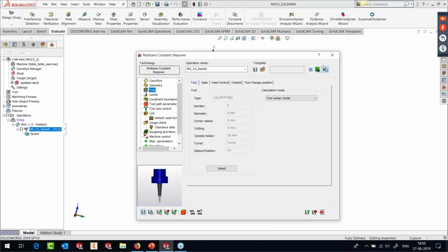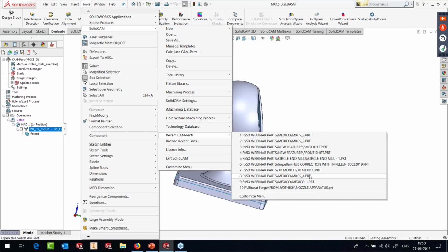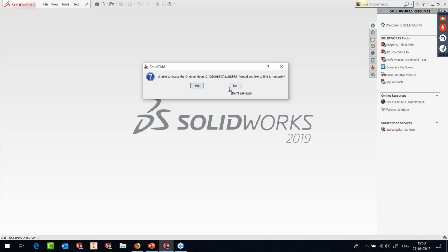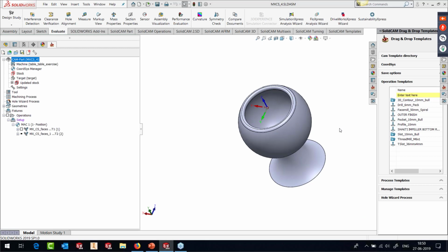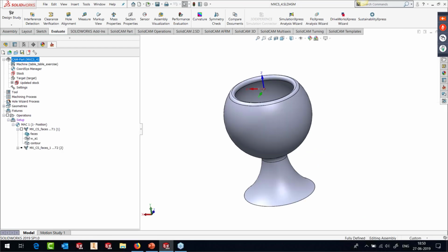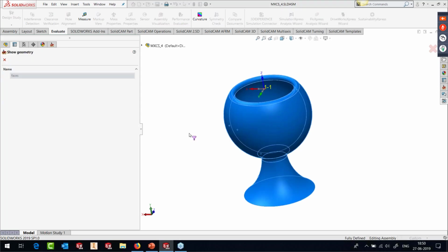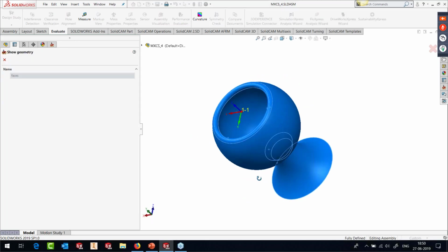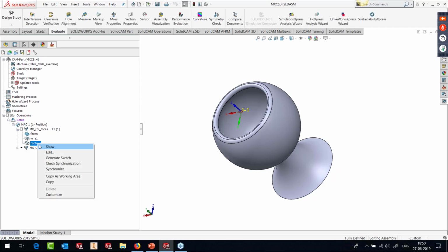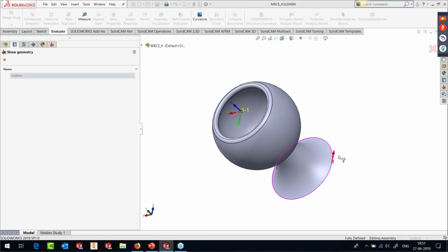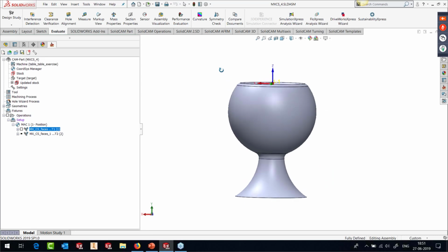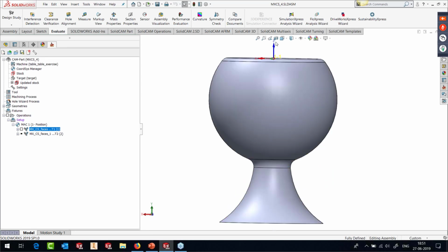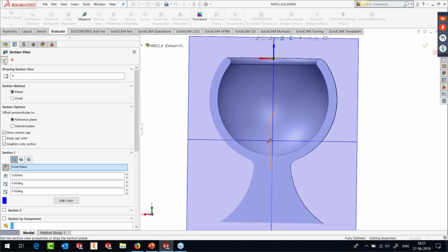We'll see another group of part or another part where it's even more nicer. Okay, in this case, I have defined a group of surfaces. Except the bottom, I've defined everything. And what I've defined here is the curve to which it needs to be parallel. The cuts need to be parallel. So what it has done basically is, you can see that it generates a pattern which is parallel to the entire geometry. So let's take a slice of the part.